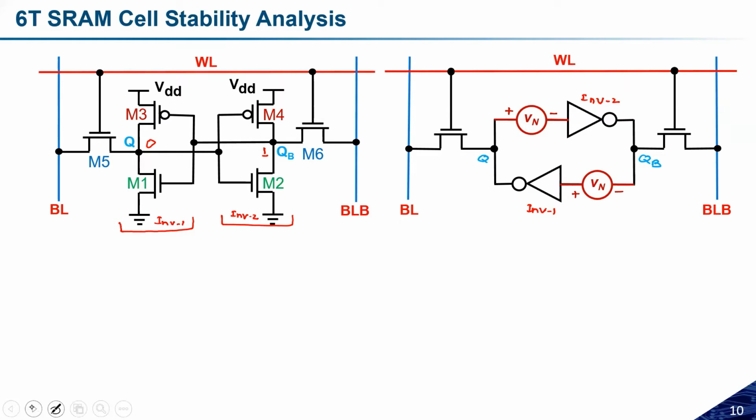Now let us talk about if we have a simulation set up and I want to perform some operations, so what will happen? As Vn increases, the stability of the bit cell will change. Initially if Vn is equal to 0, it will act as before, whatever the status of the circuit was. But as Vn increases, the stability of the bit cell will change, and the bit cell stability during active operation, especially the read cycle, represents a more significant limitation to the SRAM operation than the hold one.